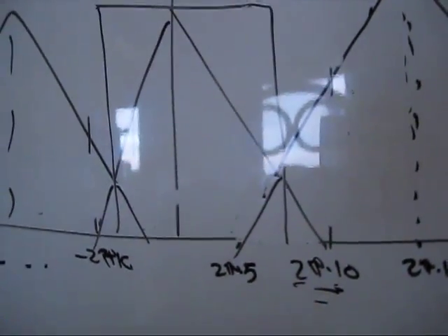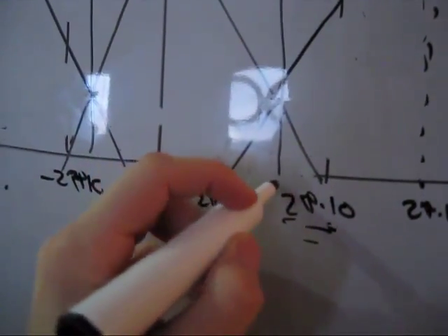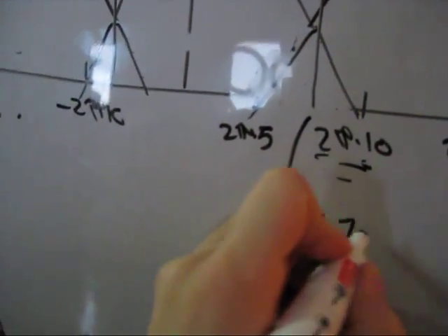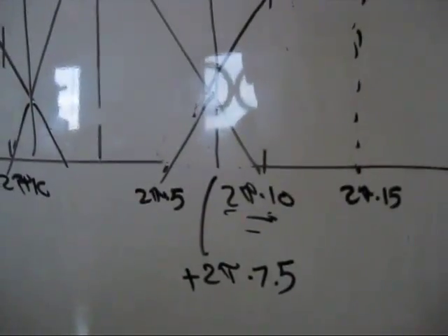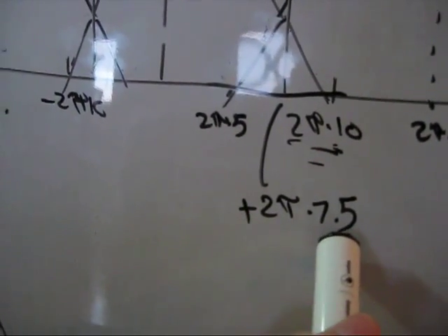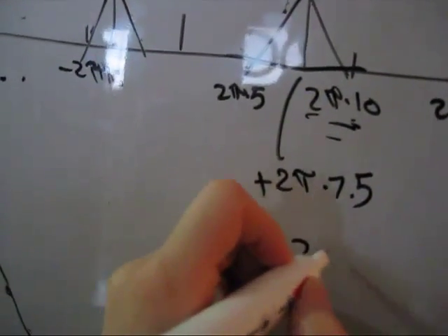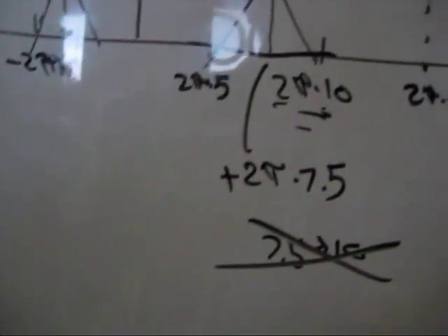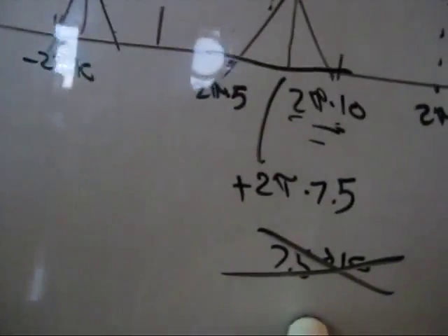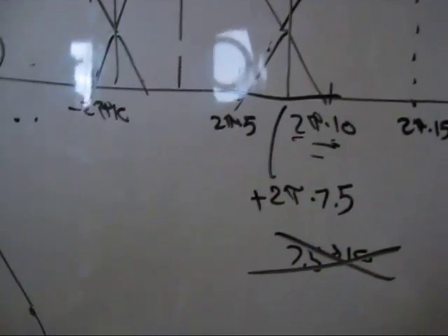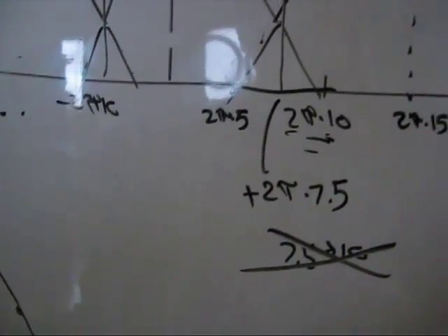Which is another problem. So basically, right here, that point is positive 2 pi 7.5, which is half of our sampling frequency, right? So basically, we've cut off everything from 7.5 to 10 hertz. All that is gone. Well, that's not what we wanted. We wanted to sample the whole signal, right? And we knew that there were some frequency components within that frequency range that we wanted.